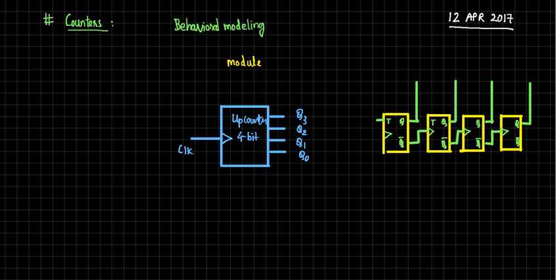The thumb rule to remember is, if the lines go in an up direction, it's an up counter, for positive edge trigger. If the lines go down, then it's a down counter, but for positive edge trigger. If it is negative edge trigger, then the reverse is true. But we always take output from the non-complemented terminals.